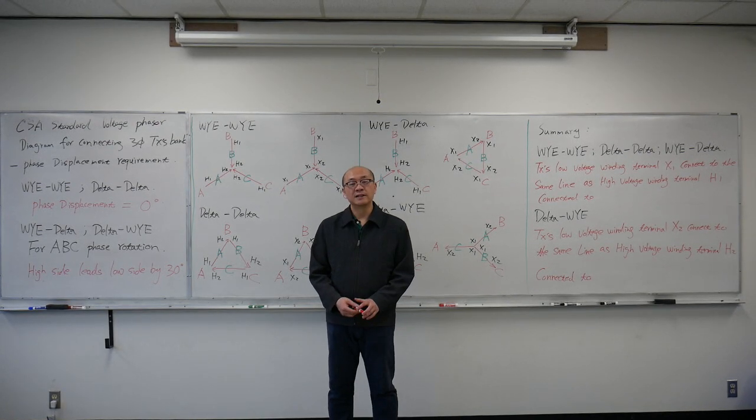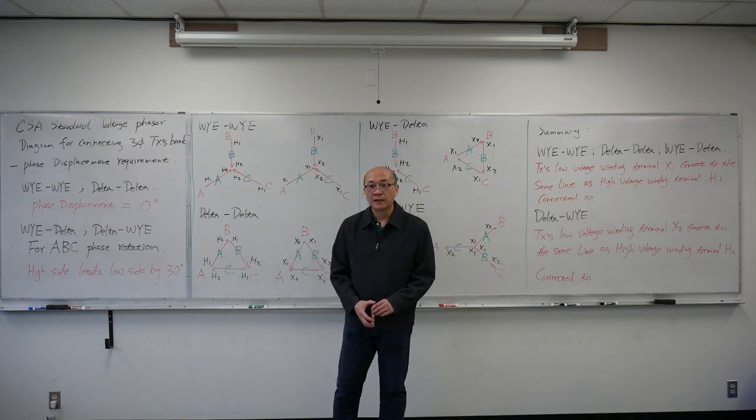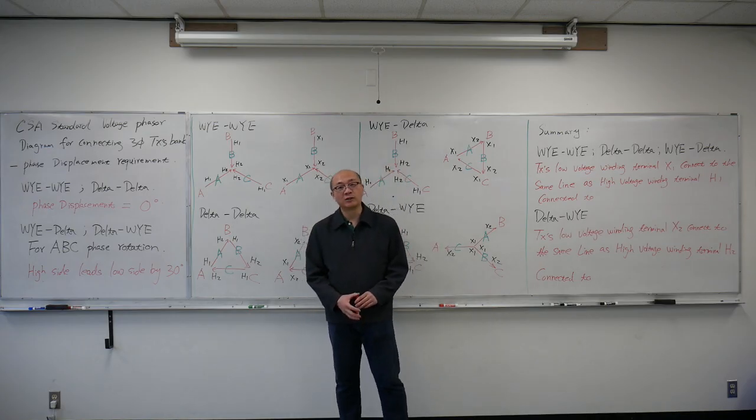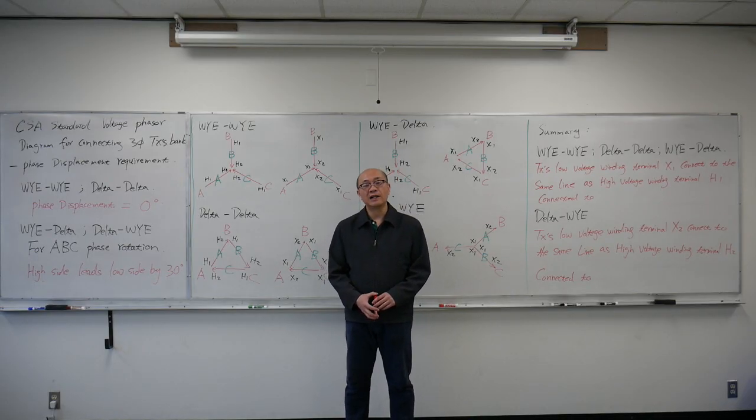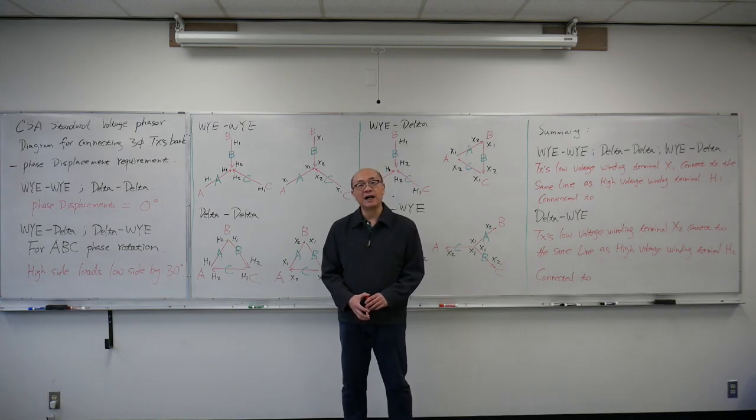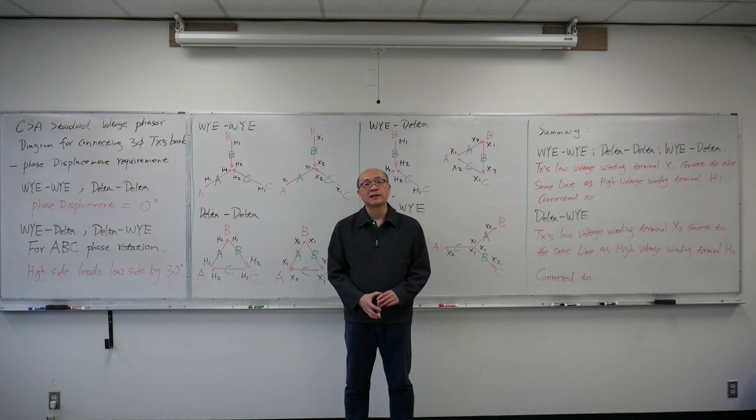Hello everyone, in this lesson we're going to discuss three-phase transformer connections. If you still remember, in second year we talked about single-phase transformer connections, where, when paralleling single-phase transformers together, we have to watch the polarity of the transformer terminals. If we don't watch the polarity and get a wrong connection, a short circuit can happen. The same thing is going to happen on three-phase transformers. If we don't make the connection right, there's going to be a short circuit with parallel transformers.